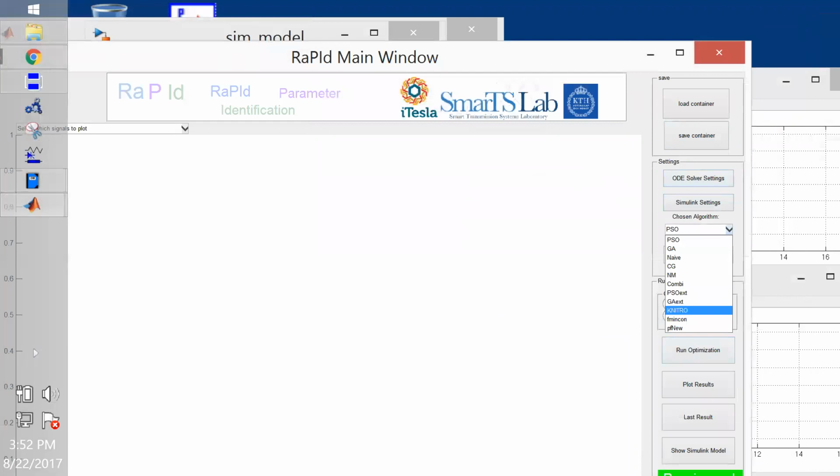It's a commercial library for optimization. I don't have it anymore, but in the project, we had to put it in. This is fmincon from MATLAB. What is the best algorithm for this? There's nothing that is better than the other. It depends on your use case. In this particular system, we had no information on the parameters of the AVR. So in that case, when you don't have a guess of the parameters, a heuristic algorithm at least allows you to find some good parameters to set.